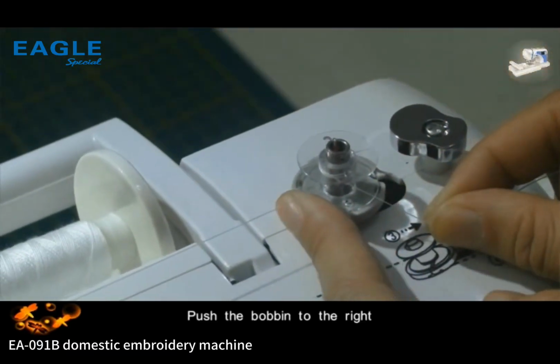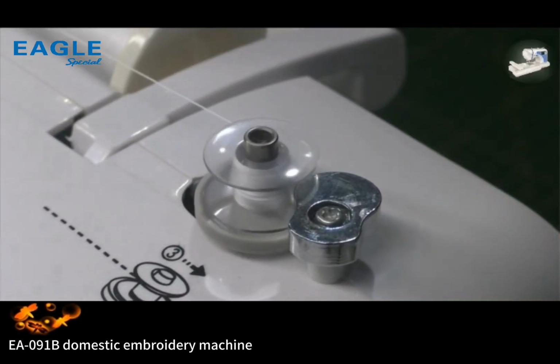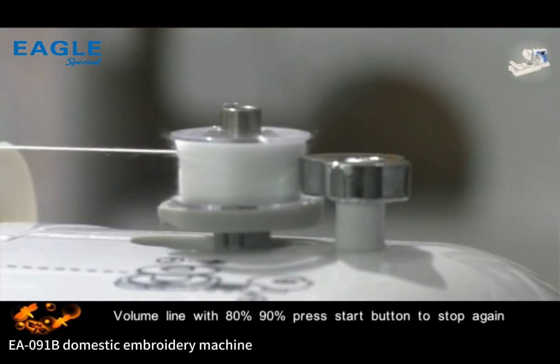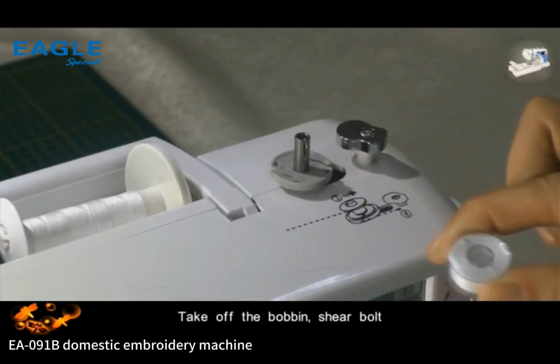Push the bobbin to the right. Press the start button to start winding the thread. Wind to about 80%, 90%. Press the start button again to stop. Push the winding reel to the left. Take off the bobbin and cut the thread with the shear bolt.